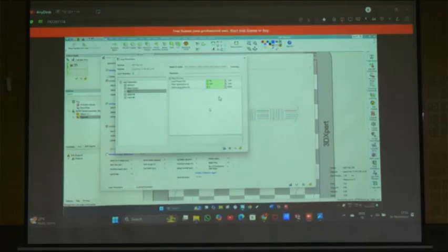Yeah. I told you, our aim is to focus on the design. One of my co-scholars has printed many lattice structures using the default parameters only. In my case, I did the process parametric optimization using solid bodies, calculated residual stresses and solid mechanical properties. Once everything was finalized, I went with the lattices, and I printed the applications using the lattices. That is how I did it.